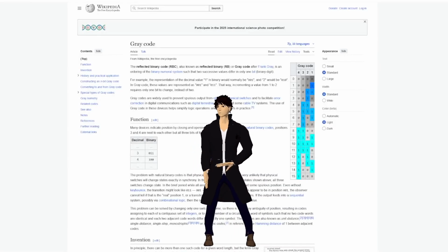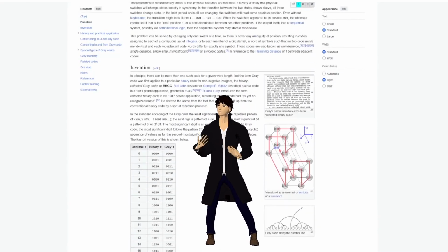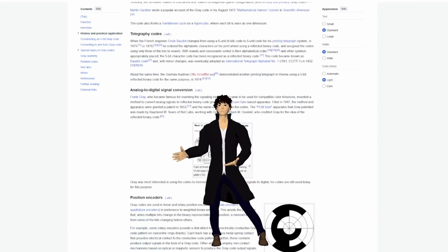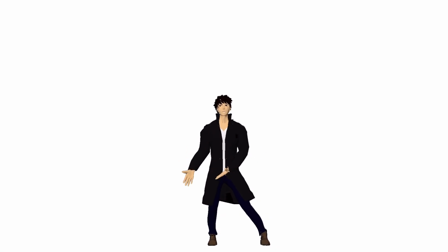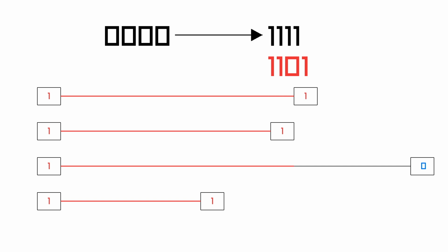For a counter or a state machine, you can encode the value so only a single bit ever changes between clock cycles. The other bits are constant, so their registers don't change, so the transistors are never at risk of being caught with their pants down. If you have a data bus where multiple bits may change, it's possible that one of the registers falls behind and the output does not match the input.